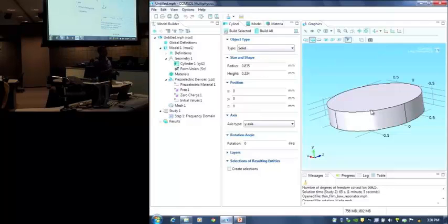You can, however, still do the modeling with the thickness in the z direction. In that case, you'll have to change the Euler angles provided by the supplier in a way that makes sense. And that is described in the model library example model, how you would begin the simulation if the thickness was not in the y direction but in the z direction.